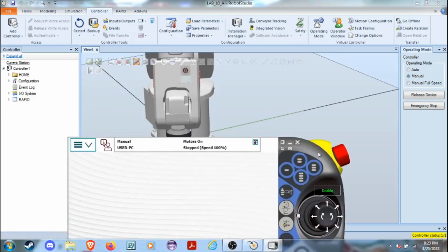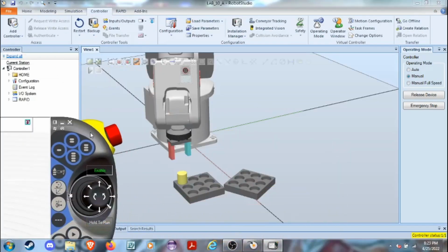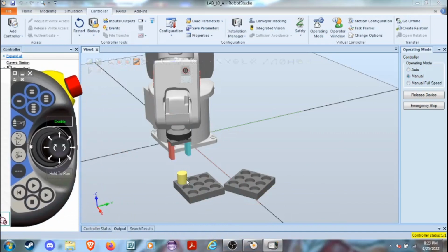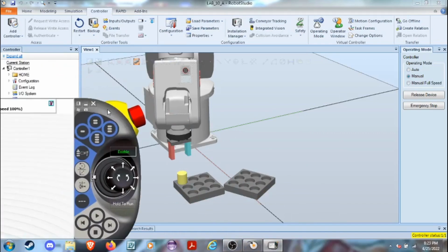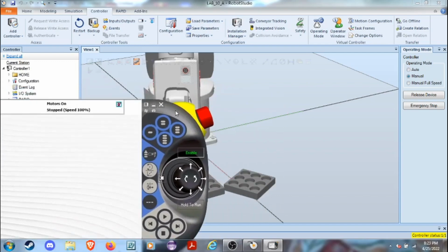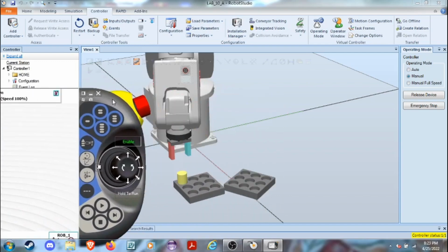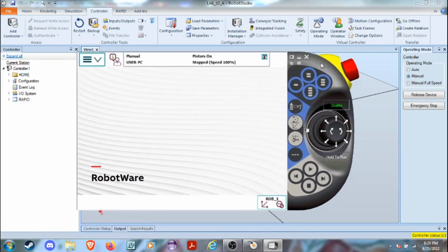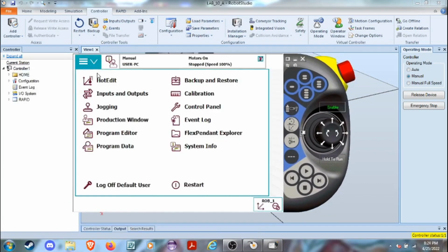After getting our gripper in order to attach to the post using the simulation logic, we now have to train it the actual points that we want it to go to, as well as the work objects. So, in order to train it with the work objects, or rather, in order to get there first, we have to define the tool object.